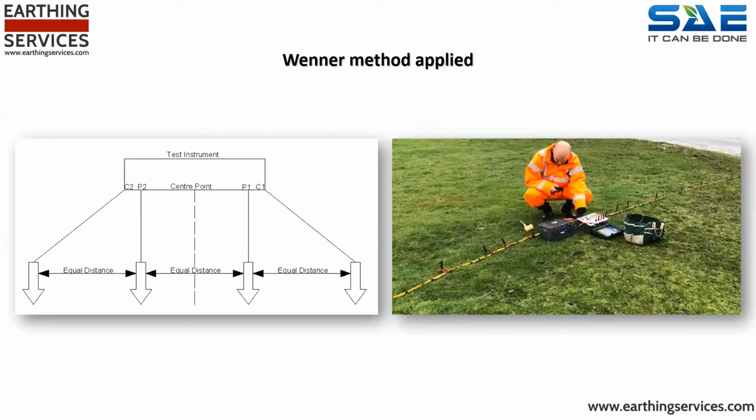For a specific location, there may be in excess of 10 different activations, with each activation being a different distance between the probes. It is important to note that these tests should be undertaken in a straight line, otherwise the data will not be representative of the site.